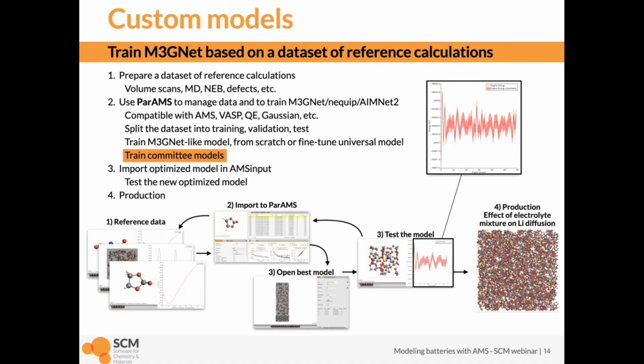In this case, the uncertainty is pretty much constant, but it could be some case where during the dynamics you're going to reach a value or a geometry with very high uncertainties. In that case, you would have to go back and maybe retrain your model. That's often the case when you use this procedure to train a model: you often end up with a test case that fails. So then you have to basically prepare more geometries, retrain the model, and iterate like that.